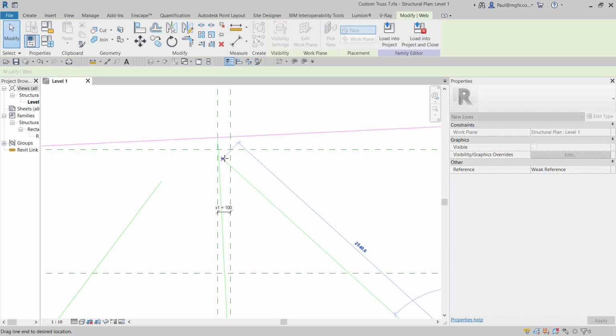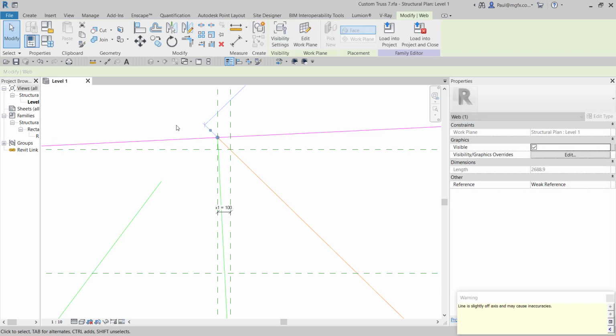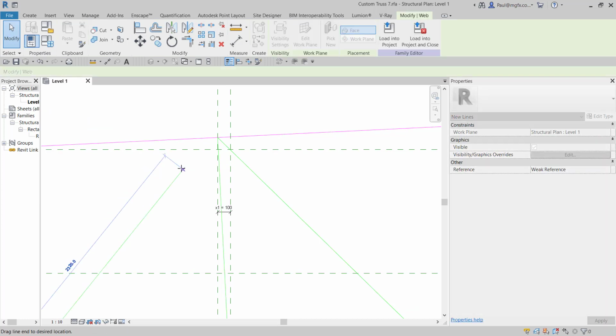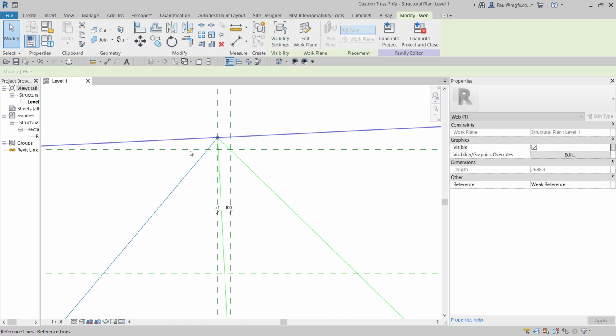I must not come in such a fashion that I highlight this one and snap to the wrong members when I snap in here. You want to snap to the ones that highlight, and that's the trick to remember. Otherwise there'll be a reference to the wrong members. And it's nothing more complex than that.